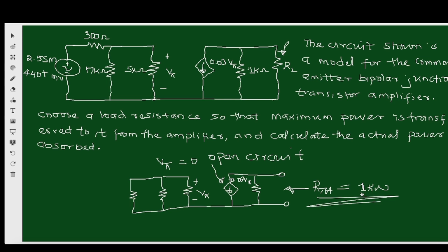So let's get the Thevenin equivalent voltage. If you look at this, that is, if you cut this out, we want to get the Thevenin equivalent voltage, right? So plus minus VTH. If you are looking at the circuit, this network on this left hand side from the right, what do we see? We only see this and this. This is usually called the collector side for a bipolar junction transistor, right? So you only see this and this. This is the emitter, right?